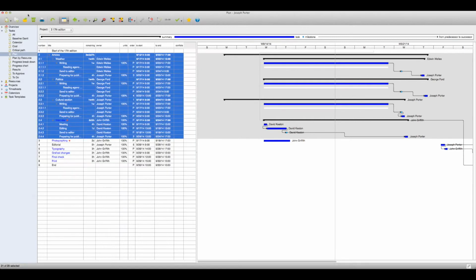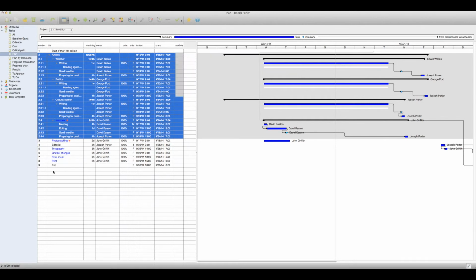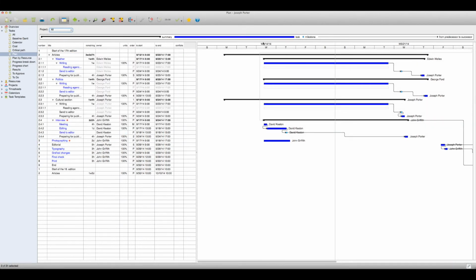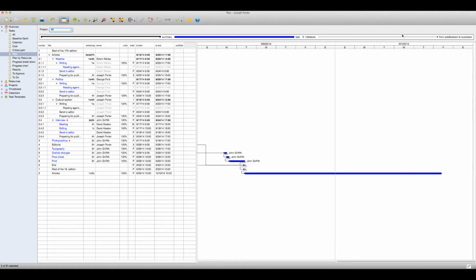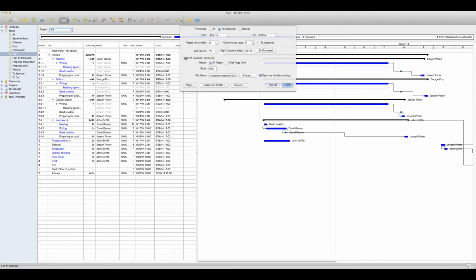If we would like to print only 1 week per page, we need to lower the count of columns per page to 1. If we are printing a bigger time interval, the count of printed pages will rise, so the report will be printed on more pages called tiles. The chosen amount of columns will be displayed on every page. For example, if we have columns in the Gantt chart set up on weeks, and we want to print 8 weeks, but we want to print only 2 weeks per page, then our 8 weeks are going to be printed on 4 pages.